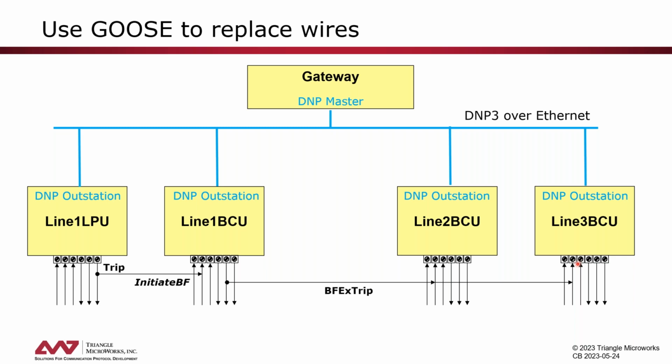So as we discussed, the first approach to start using IEC 61850 would be to get rid of this wiring and apply instead the GOOSE communication service. As GOOSE is using Ethernet and DNP3 can be run over the Ethernet, we don't need to have additional communication network infrastructure.